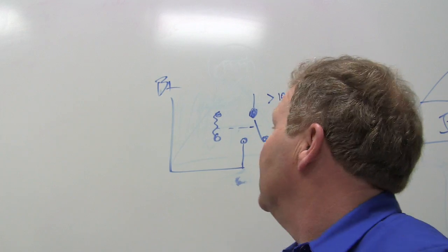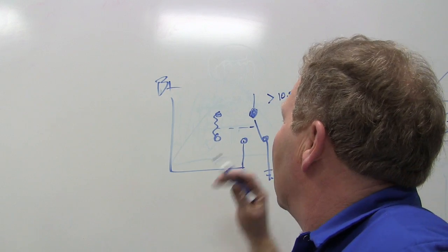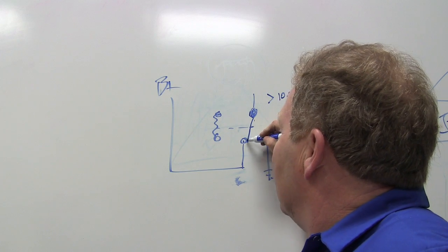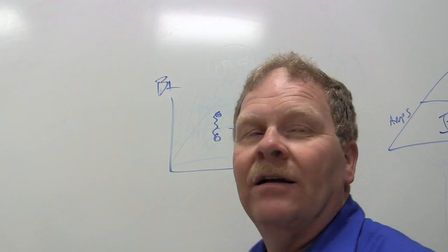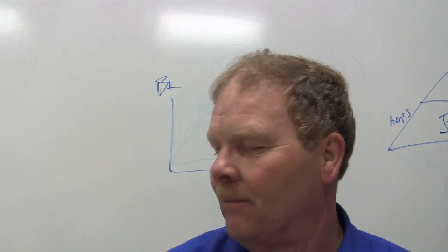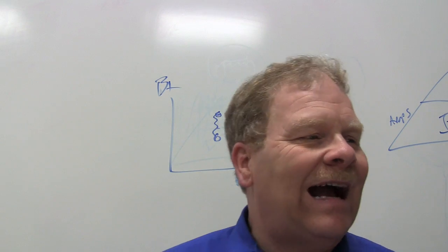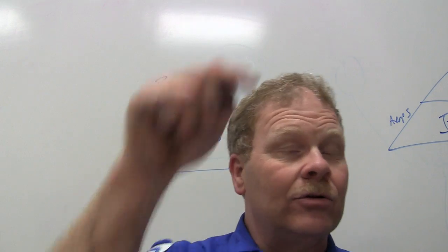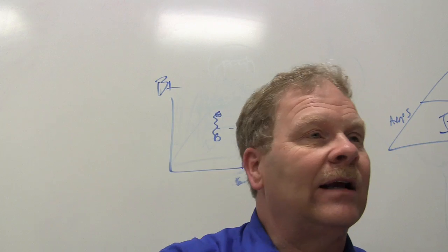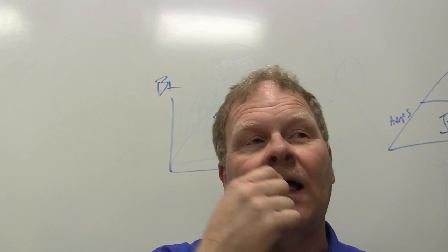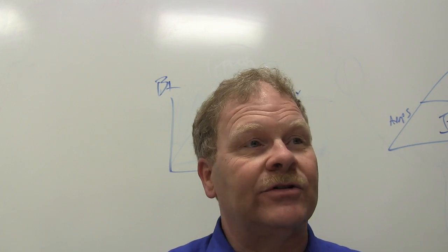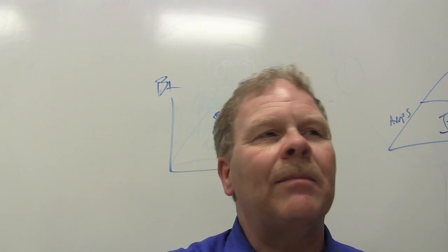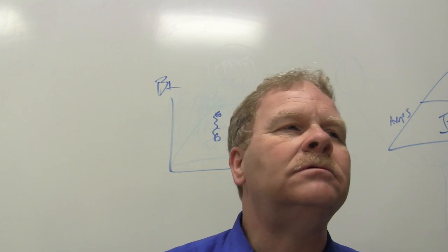That's because this right here, whenever I turned on the key and this clicked over here to the hot side, these contacts were so filthy that voltage would go through them, but you didn't have any current. I can take this meter and hold one side of it, let you ground the other one on the battery, and then I can lick my fingers and touch the positive side of the battery, and you'll see that meter show 10.5 volts or 11 going through my body, but it won't burn a light.